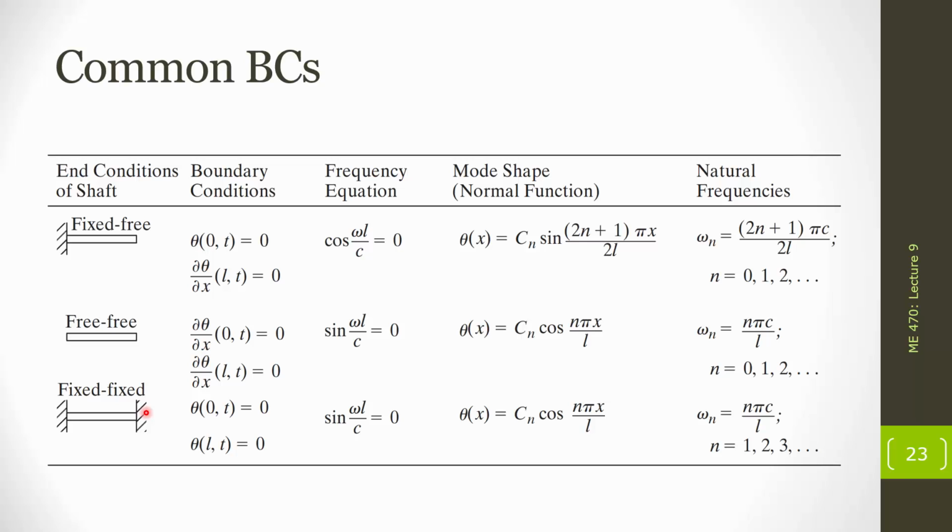And we're going to see as we go through the steps of finding our natural frequencies and our mode shapes, the natural frequencies are different when we have a fixed end. Even if it's otherwise the exact same beam, changing the boundary conditions changes our natural frequencies. And in turn, it's going to change the eigenfunctions. So the behavior of the beam changes when it's fixed-free versus fixed-fixed versus also free-free. And those are really the only ways that we can have boundary conditions, homogeneous boundary conditions, in our beams when they're in longitudinal vibration.